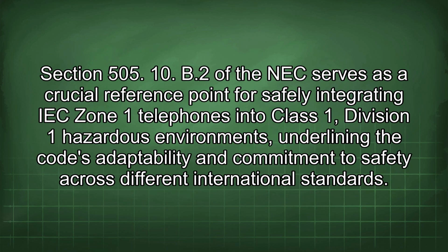Section 505.10(B)(2) of the NEC serves as a crucial reference point for safely integrating IEC Zone 1 telephones into Class 1, Division 1 hazardous environments, underlining the code's adaptability and commitment to safety across different international standards.